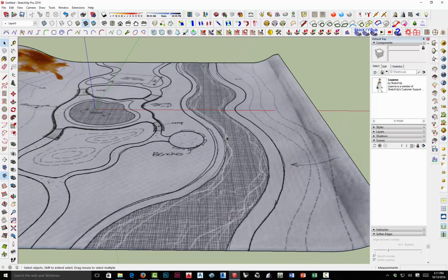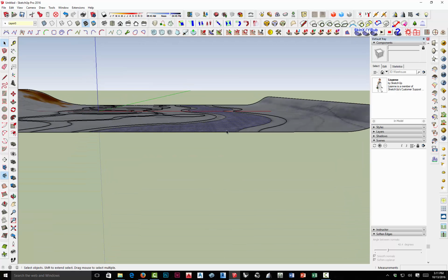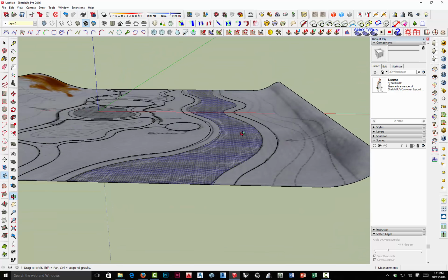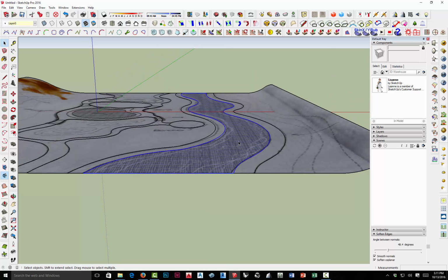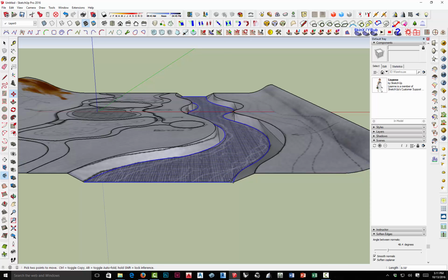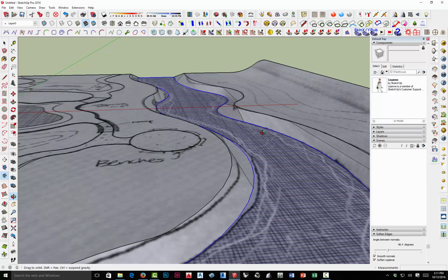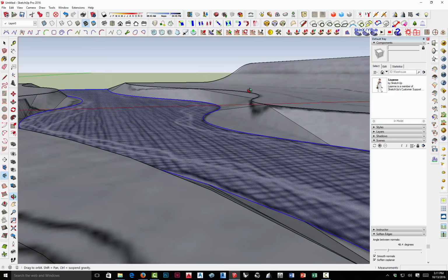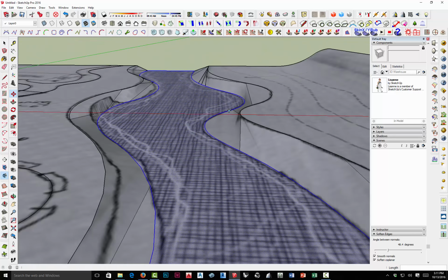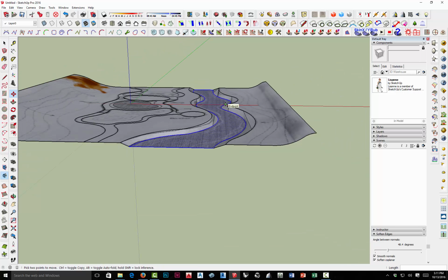Now, if you remember when we did this in class, I want to pull this down to create a lower river water level and then have embankments along the sides. If I double click on that, select the move tool, click, tap the Alt key and move that down, you remember it creates those embankments, but it really is very distorted. SketchUp doesn't do a very good job of auto folding this. It makes it connect, but it doesn't look very good.